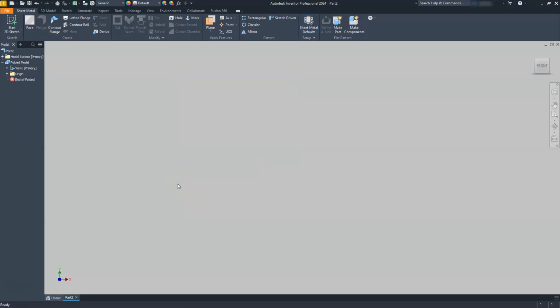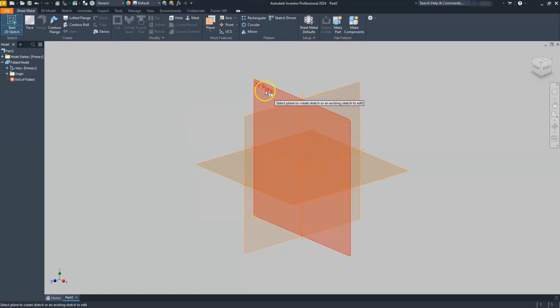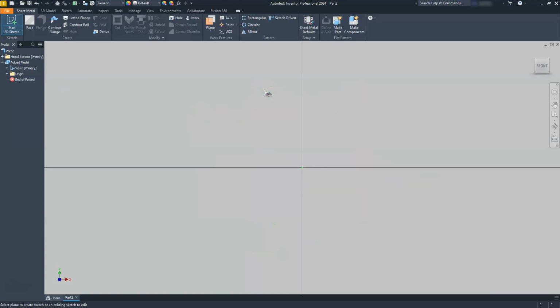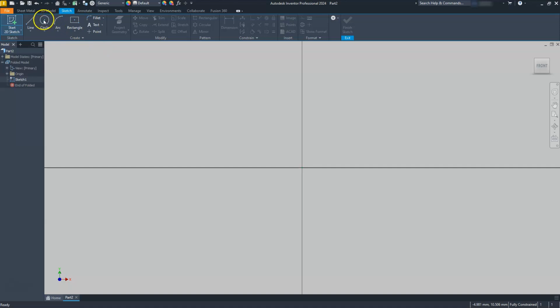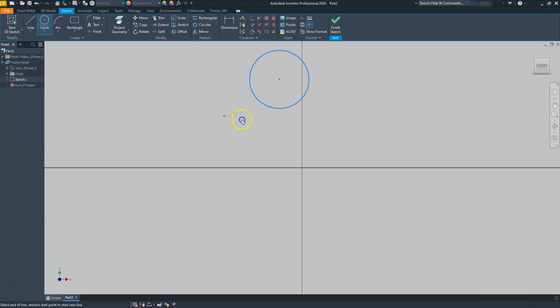All right. So like with anything that we created before, we usually start off with the sketch. So I'm just going to go here and click Start a Sketch, and then I'm going to pick the XY plane. Once I pick the XY plane, I'm going to go ahead and draw a circle. I'm just going to click it here. Let's go ahead and draw a line that goes straight across, and escape out of this. Now I want this midpoint to be at that center, so I'm going to use a coincident constraint. I'll select the midpoint here, and then I'll select this center point.